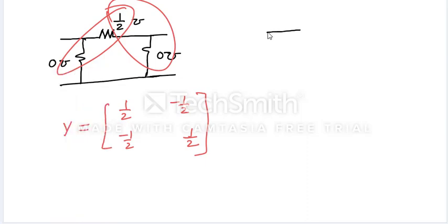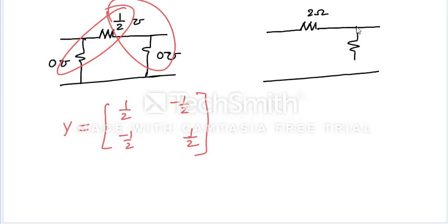Now see this network. Now we should find the T parameters also, the transmission parameters. And for the transmission parameters, the standard shape of a network must be what now here? Inverted L. Is it an inverted L form or not? We should make it an inverted L shape. There is no connection. I can call this impedance, how much is the impedance? I can treat it as infinite ohms. So now this is ZA, isn't it? And this is ZB now, both are in ohms only.